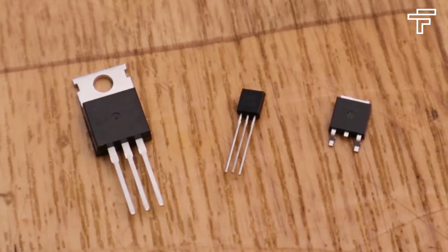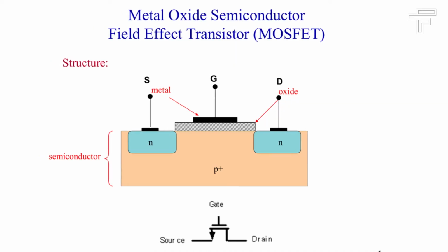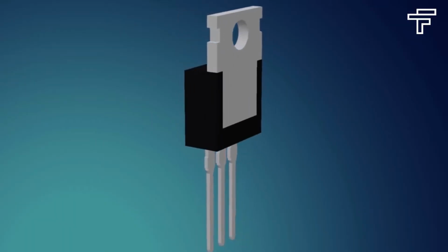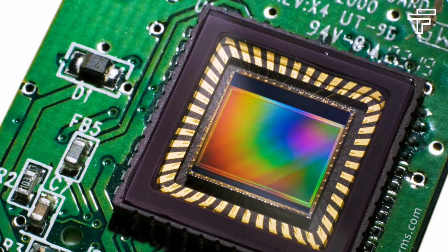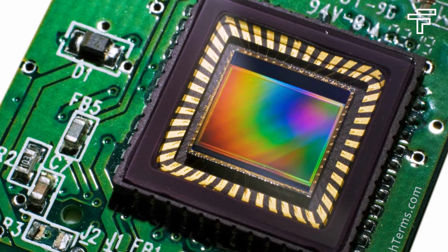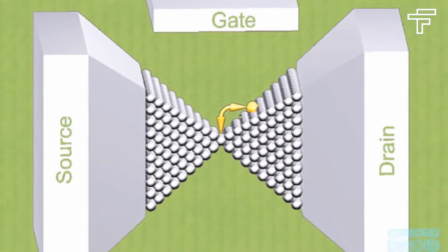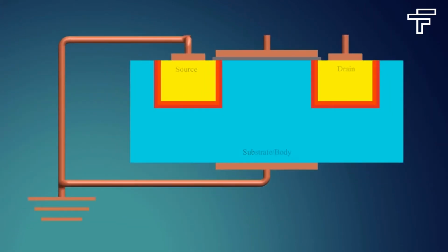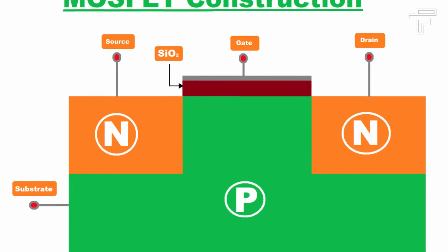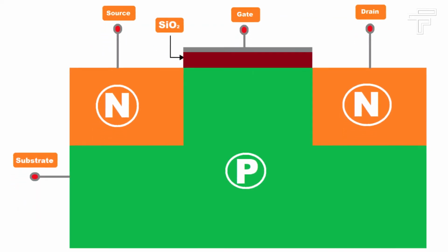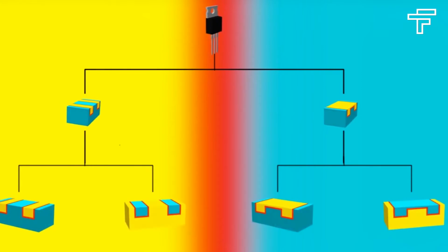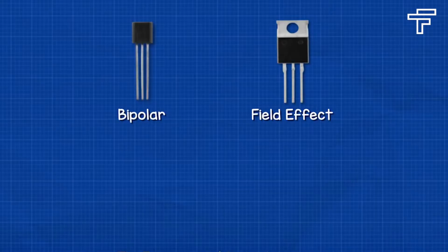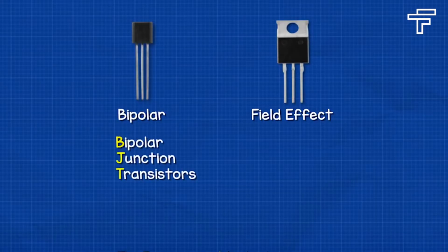The term MOSFET, full form, is metal oxide semiconductor field effect transistor. MOSFET is one type of power transistor device mostly used in VLSI circuits, CMOS digital circuits, microprocessors, and memory devices, etc. Although the MOSFET is a 4-terminal device with source S, gate G, drain D, and body B terminals, the body or substrate of the MOSFET is often connected to the source terminal, making it a 3-terminal device like other field effect transistors. MOSFET is by far the most common transistor in both digital and analog circuits, though the bipolar junction transistor was at one time much more common.